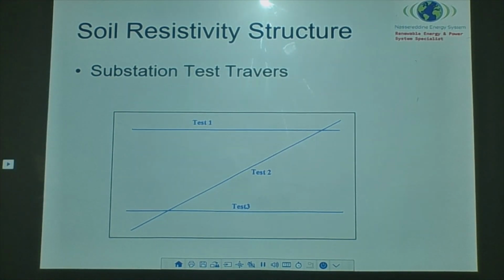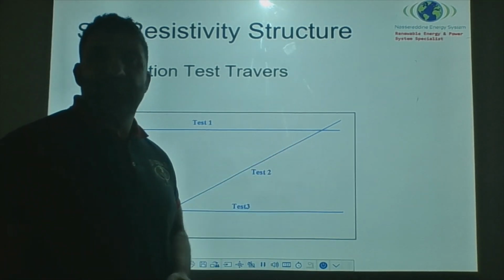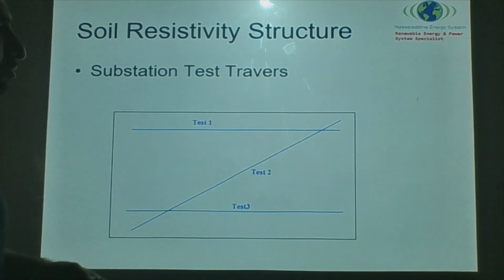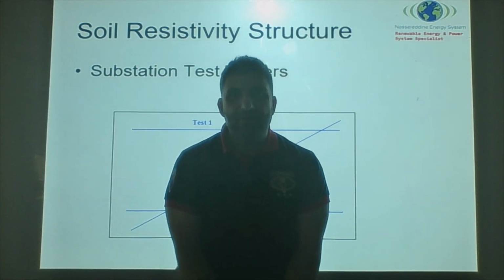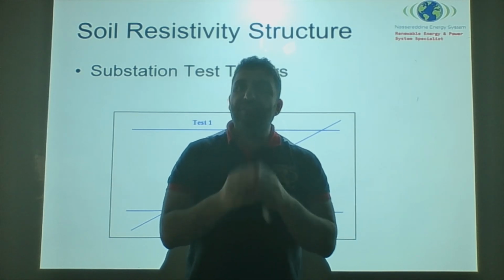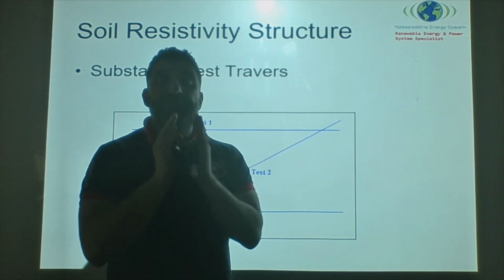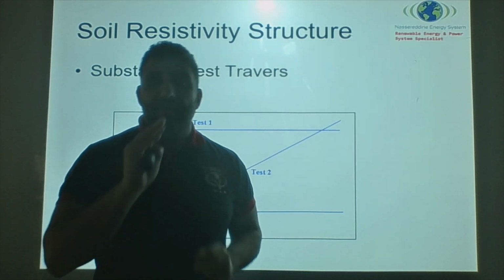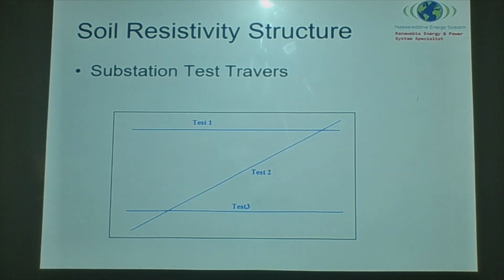So, please, avoid doing only 1 test on your site. You have to do multiple tests to make sure that it captures the entire soil area. And you have to go 300% of your size if possible. For more information, refer to our previous video.